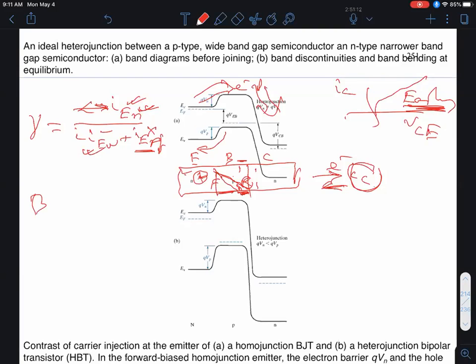All right, what was the other important factor for the BJT? That was the so-called base transport factor, alpha T. Don't confuse that with the common emitter current gain beta. So these two are different. This is my base transport factor, and that was defined as the collector current that survives the journey at this point divided by the injected current over here. So that's IC divided by IEN in this case, okay? And that, of course, is governed by the recombination losses in the base, because when I inject these electrons into the base, some of them unfortunately recombine with holes in the base, and you have to replenish those.